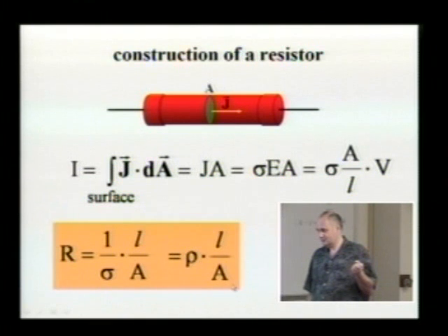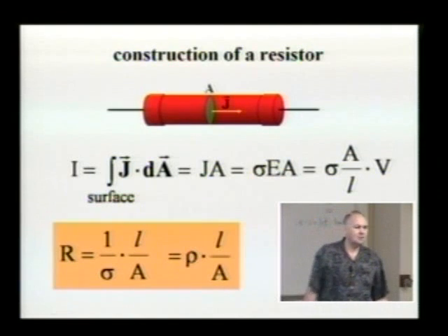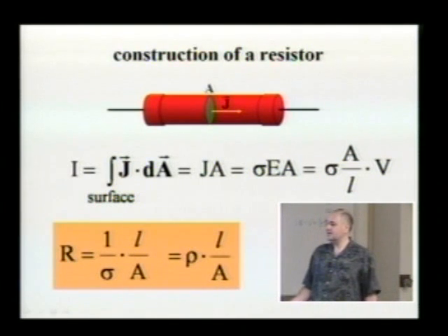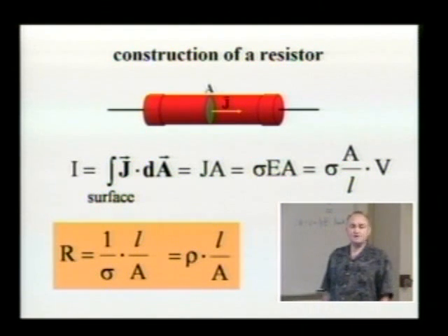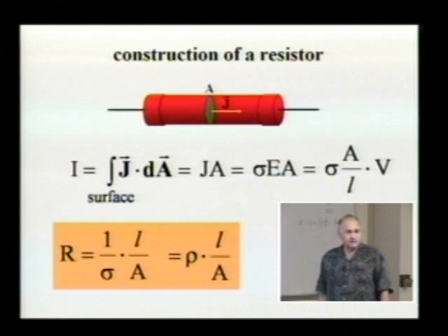Thin. Now we want to make the area as small as possible, because then we could use a shorter wire. If we make a large cross-sectional area, the wire would have to be longer. Think about it. Let's say that I want to double the resistance of a wire by changing the area. What do I have to do with the area?